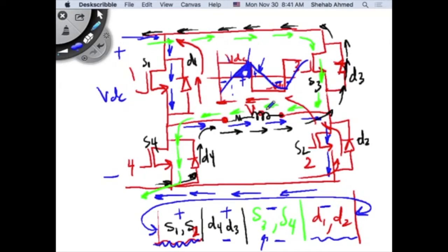But in the case of multiple switchings per cycle, we want to create a sine wave. Here, is the output current a sine wave? It's not a sine wave. It's a highly distorted waveform that we really don't like, but it's an AC waveform. So if you have an AC motor that you plug across this voltage and this current waveform, it will run, no problem.